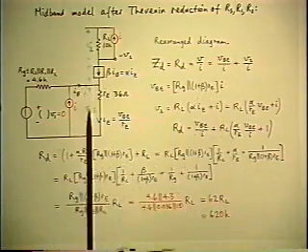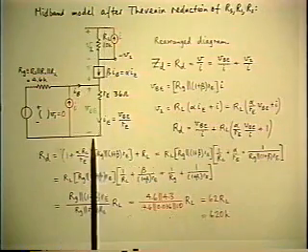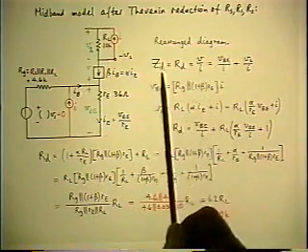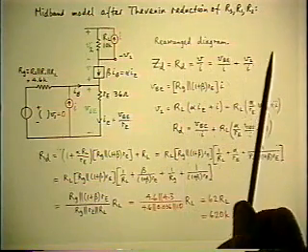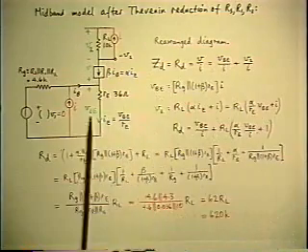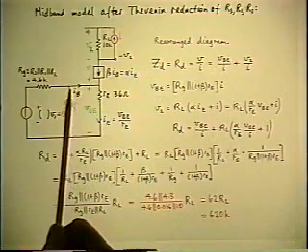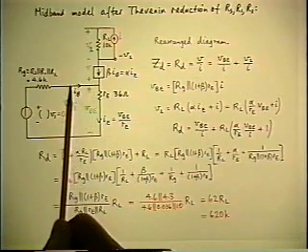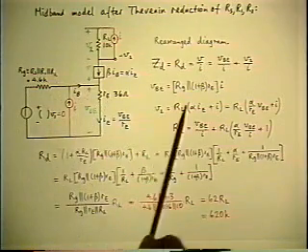I should say that the algebraic sum of all three of them is 0 because we got AC ground at the top and the bottom. Okay, so I can separate the RD into the sum of two terms. I can find the VBE as a function of I because I have a current source I developing a voltage right across it determined by the resistance RG in parallel with the reflected RE.